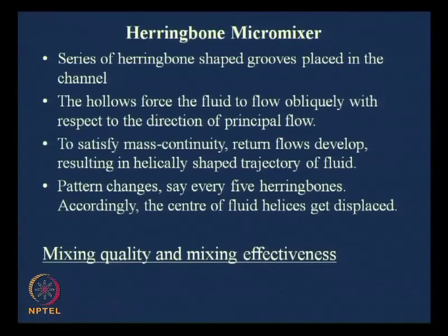Before we move on from these various mixers, in this PPT slide I would like to point out this herringbone micro mixer. We have already discussed this before. When I was introducing the lab on a chip device, I showed that on the floor you have grooves embedded by which you are ensuring cross flow. That means you have two streams flowing side by side, and grooves on the floor.